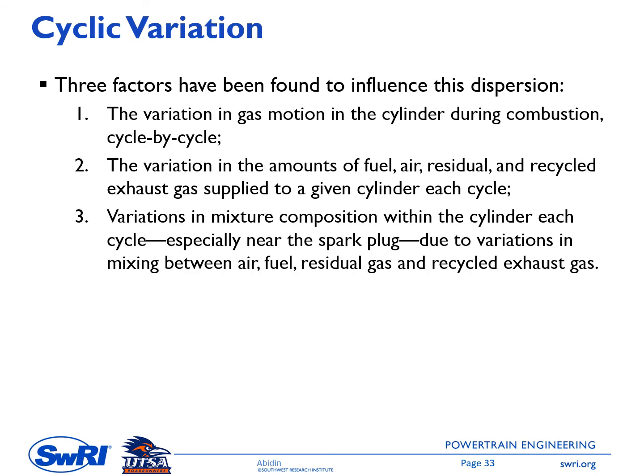And there are three factors that influence the cyclic variation. Number one is the variation in gas motion in the cylinder, and then the variation in the amount of fuel, air, residual, and EGR. The next one is the variation in mixture composition within the cylinder each cycle.